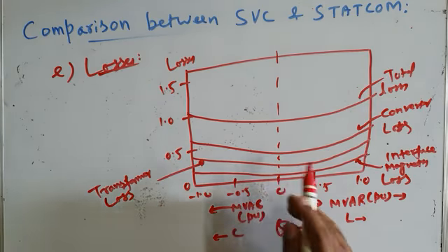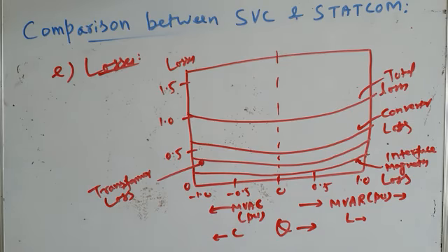But as the reactive power compensation increases in the inductive range or in the capacitive range, both in case of SVC as well as in case of STATCOM, the losses linearly increase, you can see. But the losses are slightly more in STATCOM than in SVC.